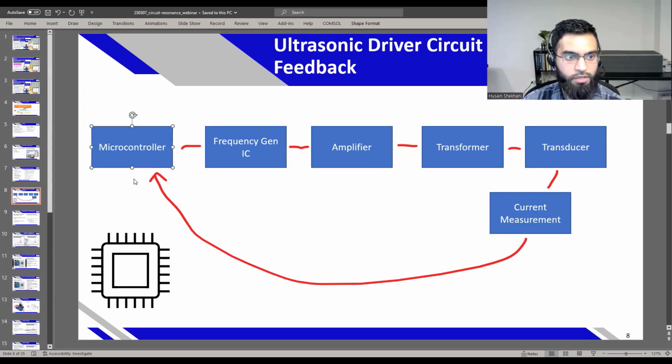One thing to note is that an Arduino can't produce specific frequencies in very small step sizes. You can turn the digital output off and on for square waves, for example, but you can only do it as far as the clock cycle is concerned. Producing very fine frequency steps is challenging. I have a whole video on clock cycle work.